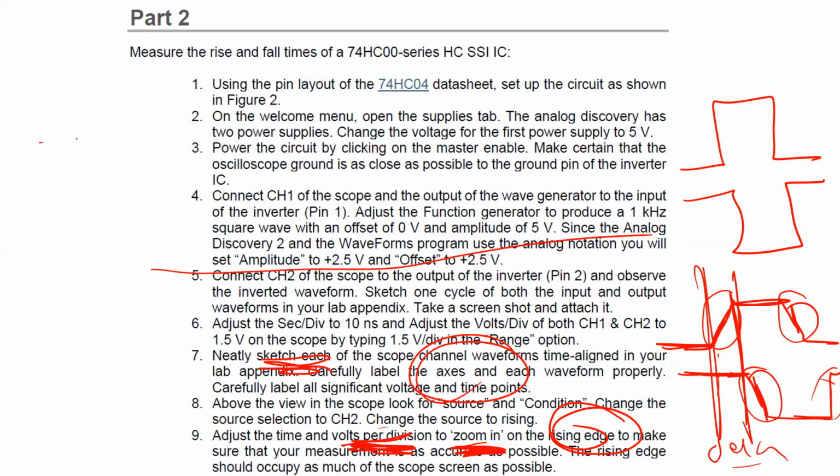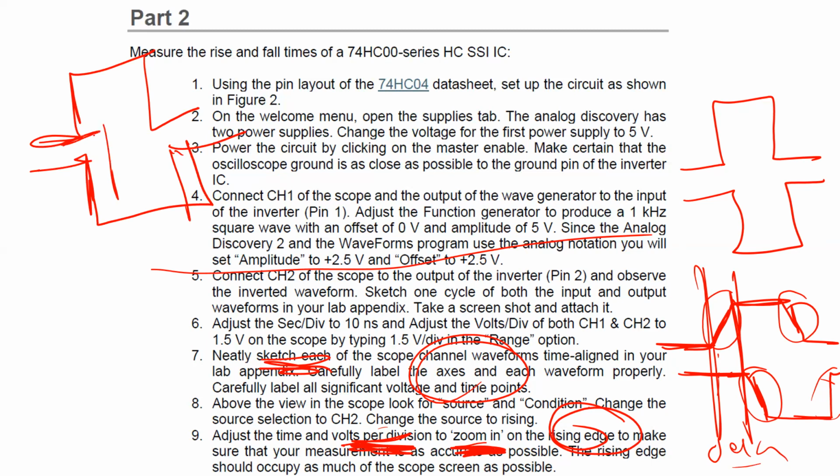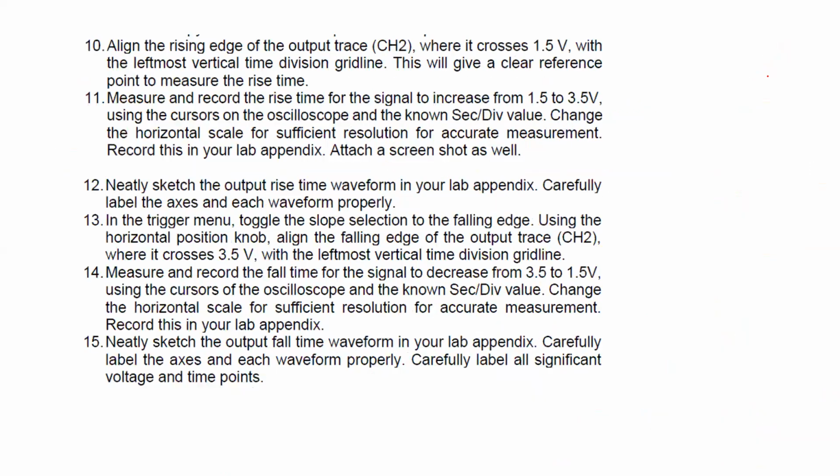Don't think that once this one is high, the device in 0 seconds is going to be low this way. No, that's not true. What happens is that there is a delay. The device takes some time to act, to open the transistor, close the transistor, so it takes some time. That's why there is a delay. So you should see a delay. This is the ideal case.